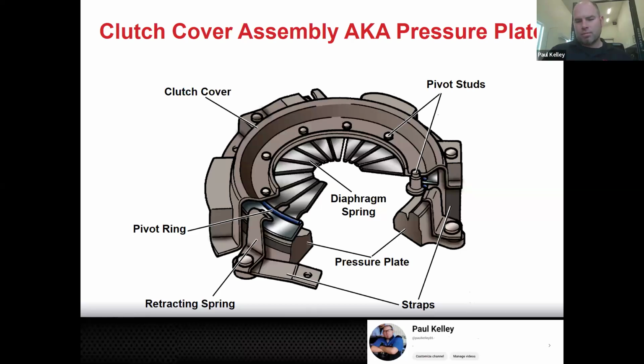There's at least air in the system, if not a totally destroyed clutch master piston seal, right? So that type of thing. And then from there, this is where it'll pivot a lot of times. There's also going to be some internal stuff where this pivot ring is going to press on the actual pressure plate. The real pressure plate is the metal part like a rotor where it's going to actually contact the disc.